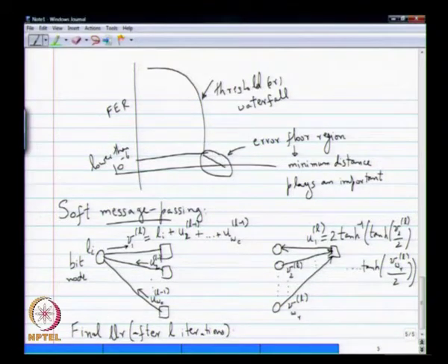After the L iterations, the final LLR is written as Li. Now you add everything. When you compute the final LLR, there is no extrinsic, so all the extrinsic information has to be added together. Now you are not trying to pass back something to anybody else. You are trying to make a final decision. So you simply add everything.